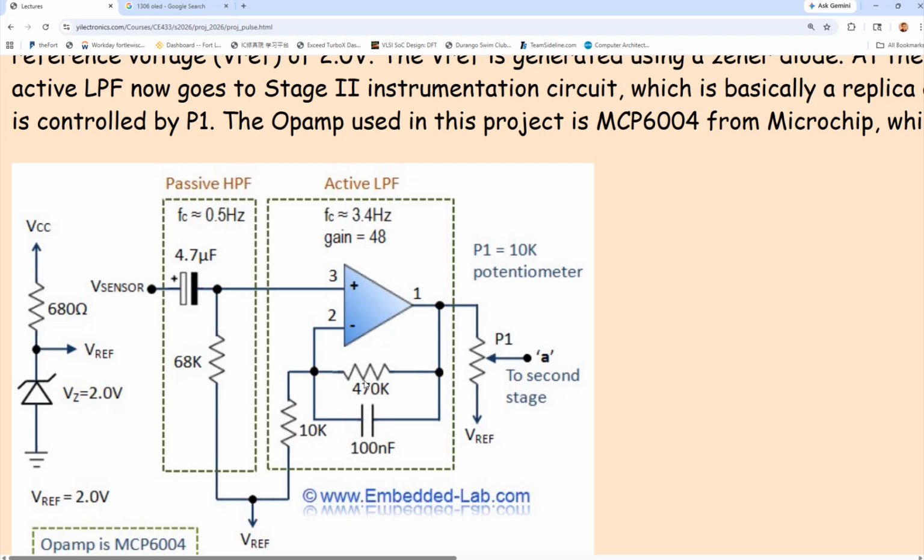So a low pass filter only passes low frequencies, right? So a high frequency signal will be attenuated. And then you are getting a lower voltage output. So which means V out over V in will be lower, which means the gain will be lower, right? So that's why I'm asking you about the DC gain. DC gain, because AC gain varies depending on the frequency, given the AC curve of the transfer function, right? So what's the DC gain?